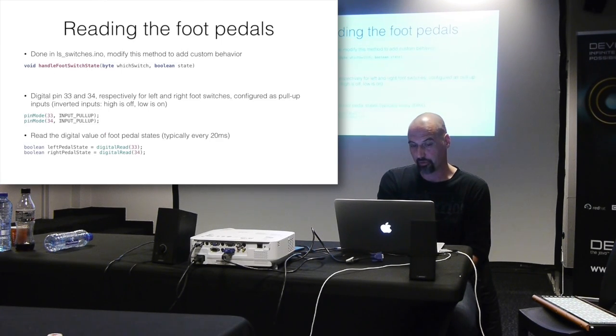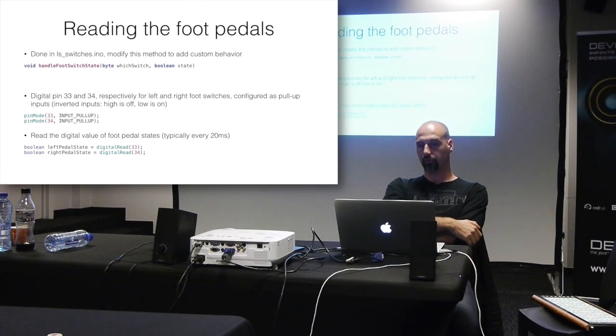And then the foot pedals are very easy if you want to connect those. They're just digital pins. You configure them, say, okay, pin 33 and 34 is a pin that I want to read. It's an input pin that's called pull up, meaning it's reversed, and high is off and low is on. And then you just read the state. So quite easy. We didn't really make any abstraction for that.